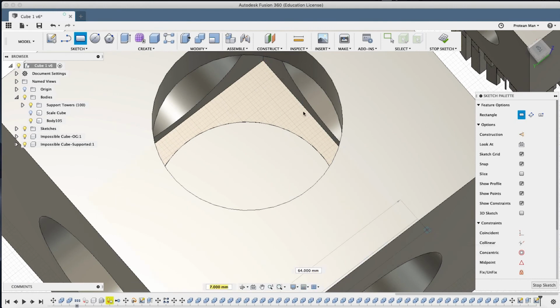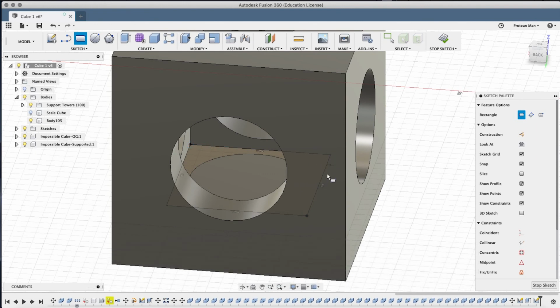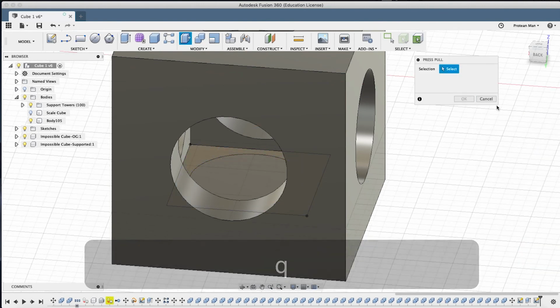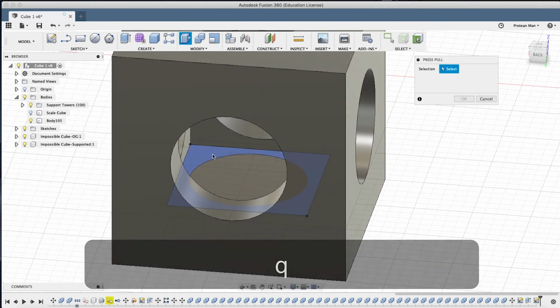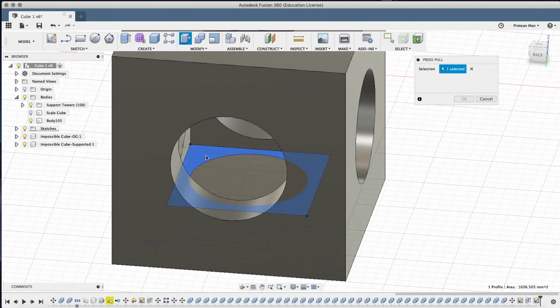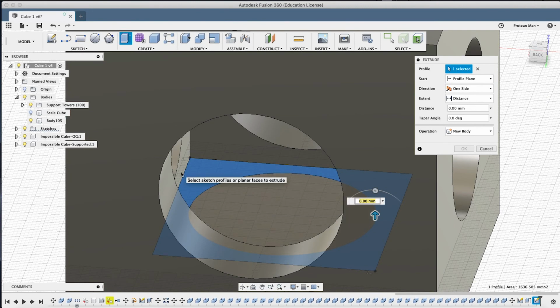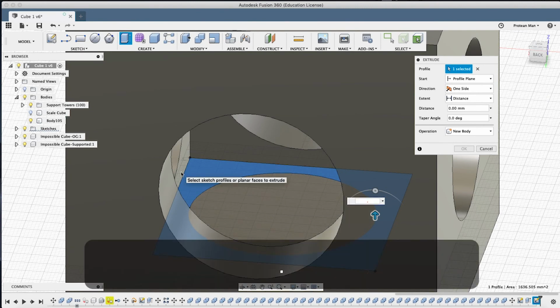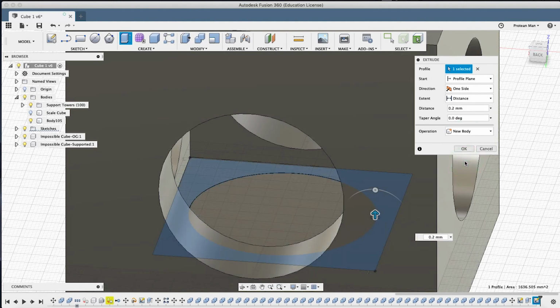There we go. So now I have a square that is the exact size because I dragged it to the snap points in the corners of my inner cutout cube. Hit Q or stop. Actually, if I cancel it, stop the sketch if you want as well. Hit Q. Now select it, and what's going to happen is it will select it all except for what this middle cylinder has. I'm going to go up just 0.2, and it says join. I don't want join. I want a new body. A new body. This is not going to be part of the large cube. A new body.